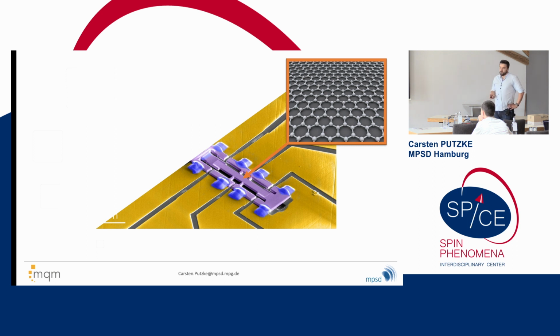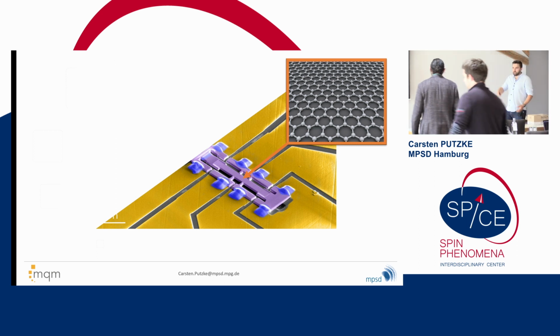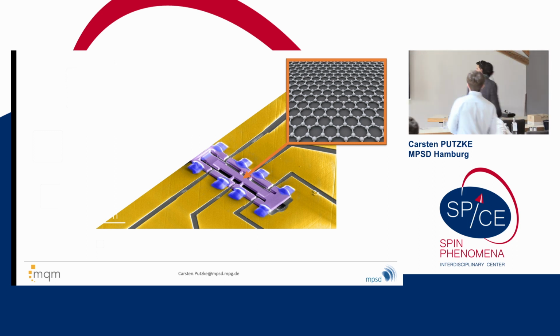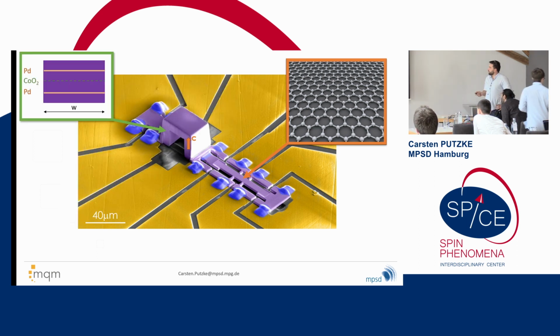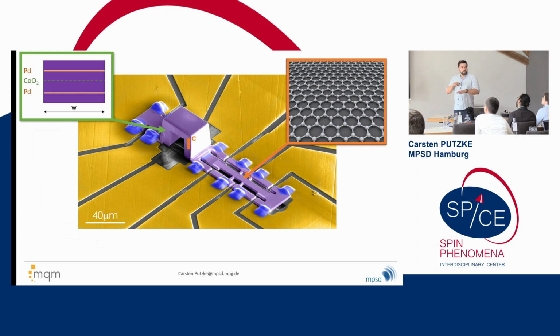And this is kind of like your graphene example, just that you have not one sheet, but 1,000 or 100,000 sheets of that. But because we start out with a bulk material, we can actually go one step further and also look at the out-of-plane conductance. So we can really make three-dimensional structures where we now pass our current down the sample, we go up in the c-axis, we go back down, and with this we can also probe the interlayer transport between these materials.